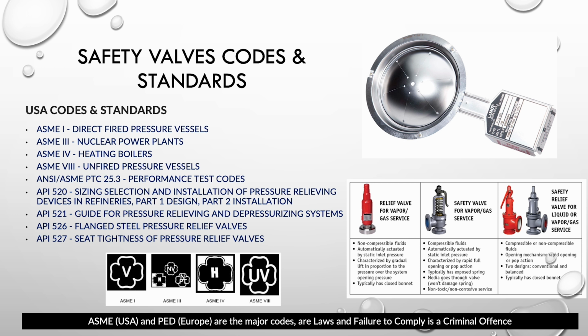What's going to need to be verified later, not necessarily by a chemical engineer anyway, is by a material scientist or a quality specialist with a certain certification. They will need to make sure, as you see on those slides, that the stamp of the ASME is on that valve. So not only do you need to specify those relief valves, you're going to need to make sure that those relief valves got the stamp of that code.